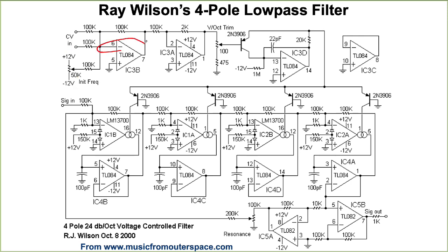And we're mixing those with this op amp here. And that would give us a negative voltage, where in previous lectures we were talking about VCOs, we might take this directly to the base, or actually we would take that and drive it into the top of this trim pot here. That was okay there because the NPNs wanted a negative voltage relative to ground in this kind of configuration. But here, since we're using PNPs, this needs to be a positive voltage here, so we need to have this other op amp here to invert the voltage back.